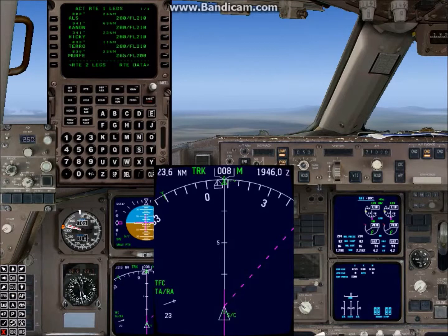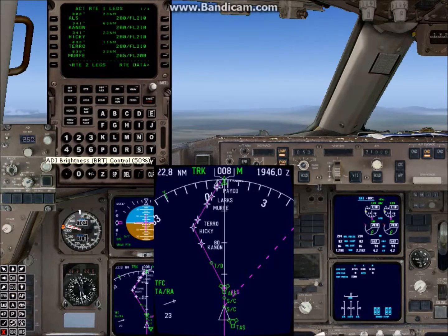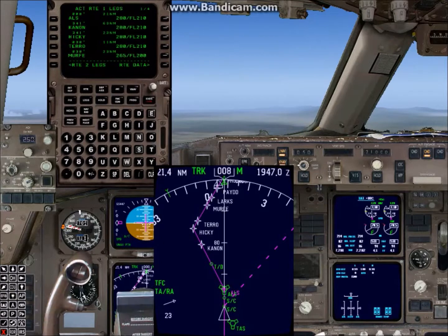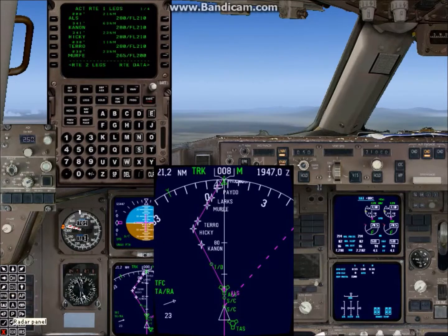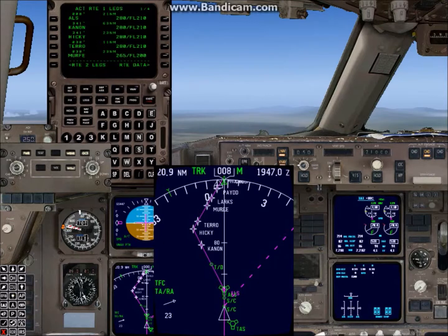And if you see that TOC point right out there, that means stop at cruise, by the way. Just another little tidbit. So pretty soon here, we're actually going to cross the Alamosa waypoint in about 21.5 nautical miles. And that's where we're going to start the Lark 7 arrival, Falcon transition, direct to the runway 35 Yankee RNAV GPS initial approach fix at Croup.